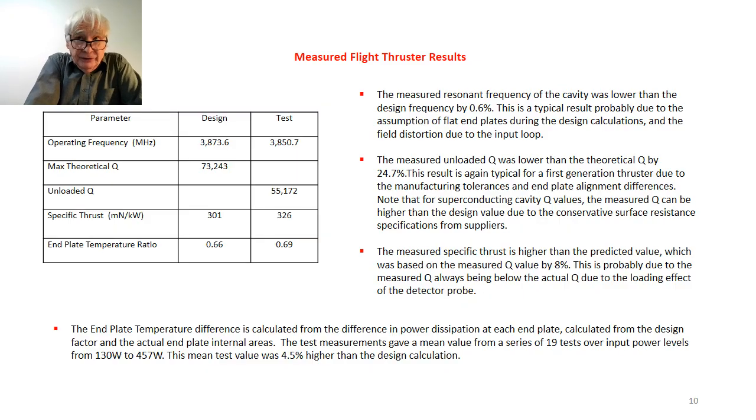You'll remember during the earlier part of this lecture, we said we make the loading of the detector probe as low as possible, and it looks like in this case the detector probe was loading the measured value of Q by about 8%.